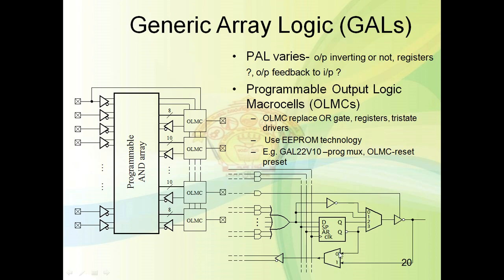And another mux is there, a 2:1 mux, and this 2:1 mux provides feedback for the sequential circuit. Feedback for sequential circuit. The output driver in high impedance state provides direct input from the component pin. So output drivers are there, and any pin is not directly connected here. In the case of programmable, in the case of generic array logic, it will have EPROMs.